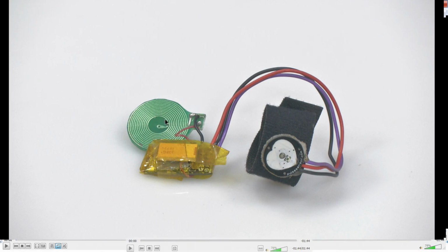It induces a certain amount of voltage output. That voltage output is stored into a capacitor. What you see, this flat thing here, is actually a supercapacitor. All that energy is stored there, and once the energy is stored, a smart piece of electronics switches on the electronics down below. Then once the electronics switches on, the power to this sensor is also made available. The whole system has sufficient power to make a reliable measurement.